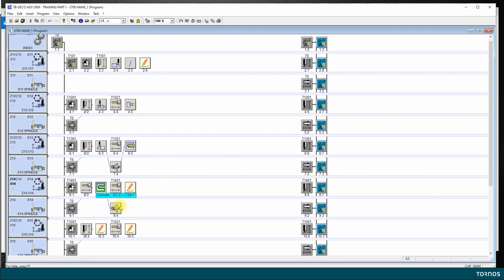So I go to the end of this operation box until I see the anchor. I press the left button of the mouse down. I keep it pressed. I move to the beginning of the operation where I see the anchor and I release it. So at this point, the speed change is in place with the right constraints. And that's it for this operation. In the next video, we will go through the programming of the tapping itself.